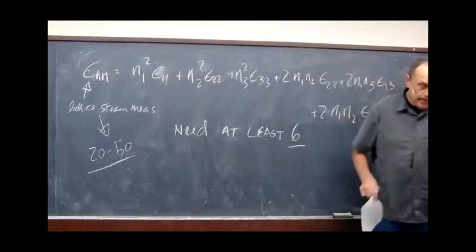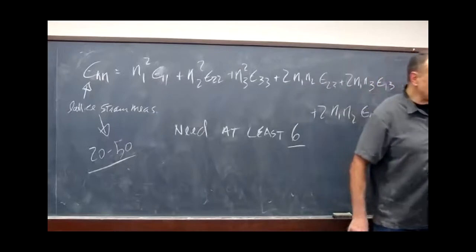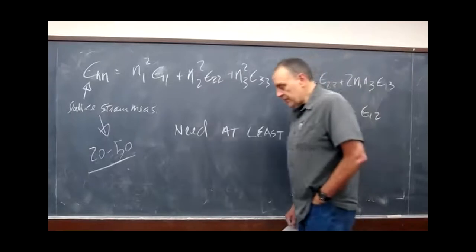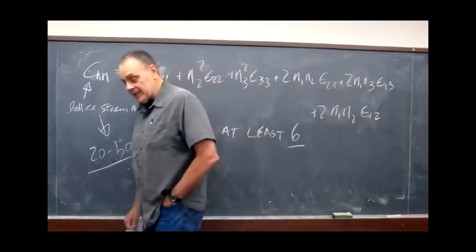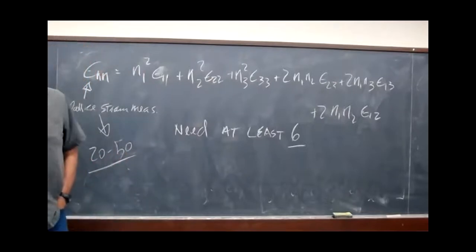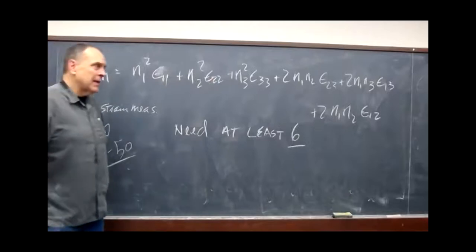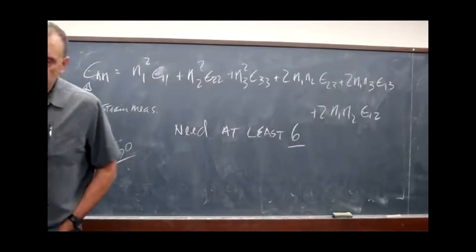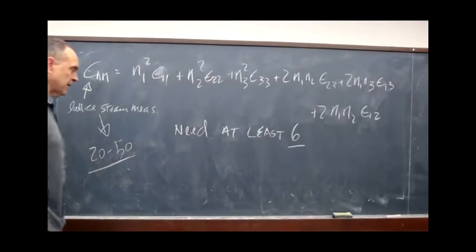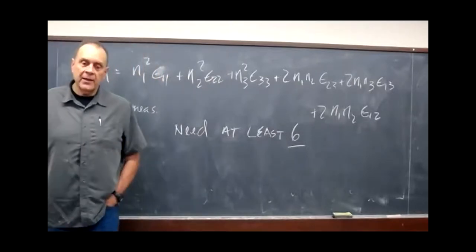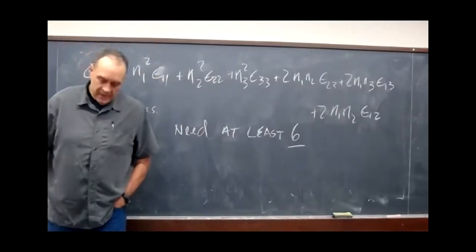So I need at least 6 measurements. For a crystal under a general state of stress, I need at least 6. This is something to remember, because right now we're talking about lattice strain measurements for individual crystals, but this generalizes almost perfectly to looking at a powder sample, where now we're interrogating lots and lots of crystals.